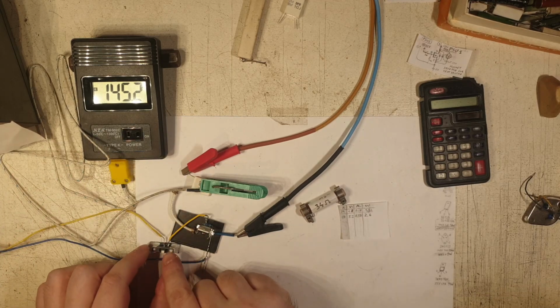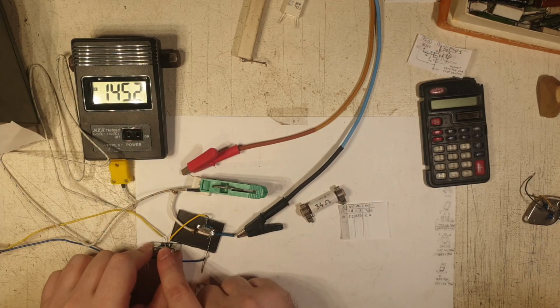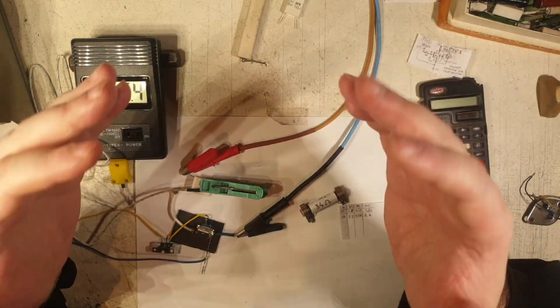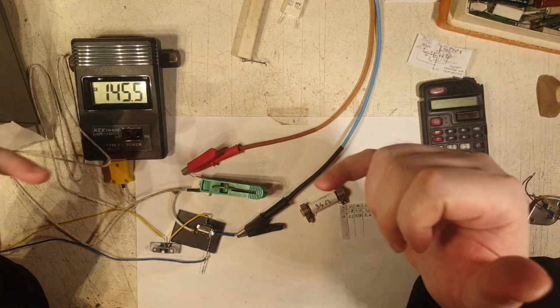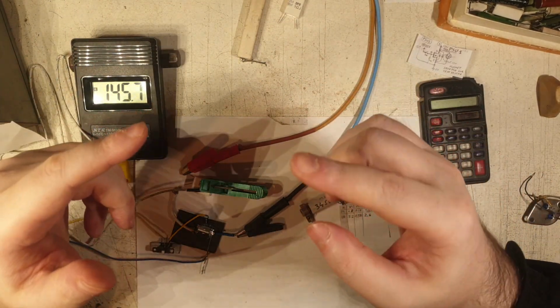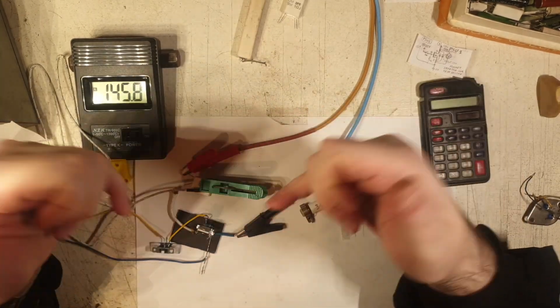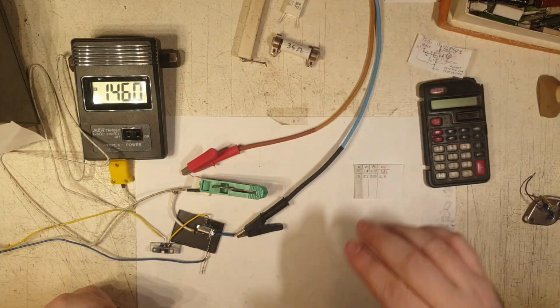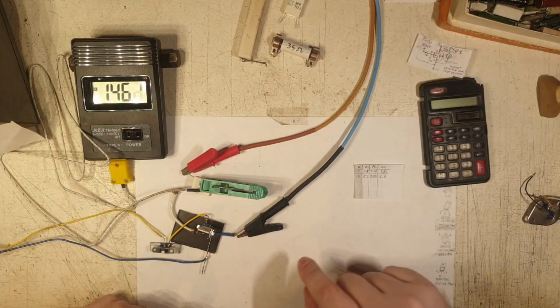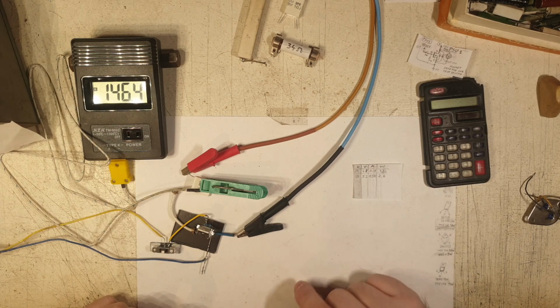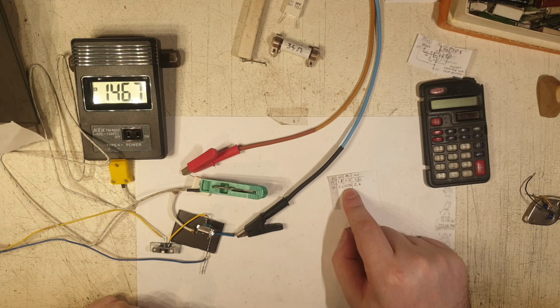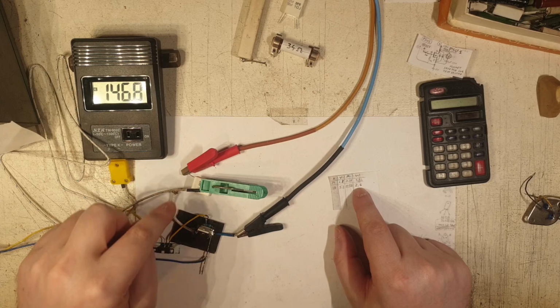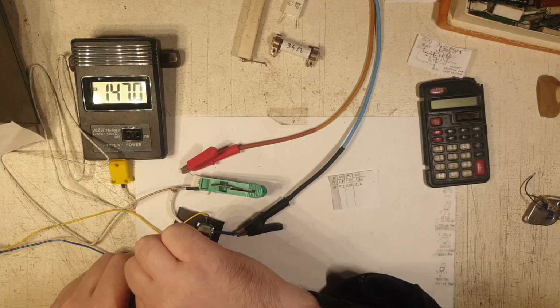But if I'm doing the test right now, it will decrease the temperature. So let's do the exact same test that I did last time. Last time I did this test with 5 amps, when it was switching from voltage to amperage, and it burned my MOSFET. So I will do the exact same test right now with this configuration, having this 10 ohm resistor there with 5 volts and 0.5 amps at 2.5 watts over that resistor. So I will do this test like this.